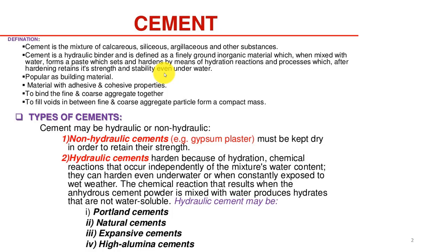So coarse aggregate has a larger size, and the space among the coarse aggregate particles is also much higher. So we use some inert fine aggregates or fillers to fill those macro pores among the coarse aggregate particles, so that we can have a pretty good cement paste matrix.